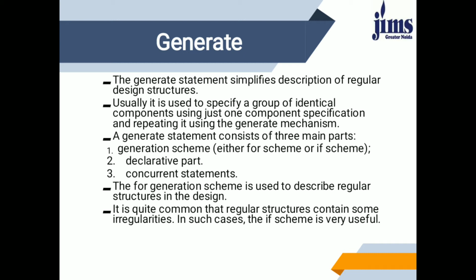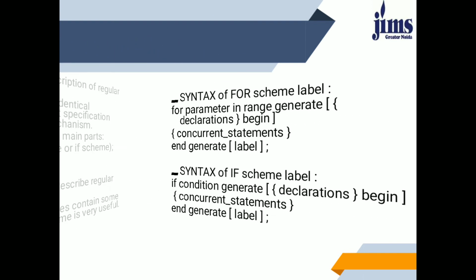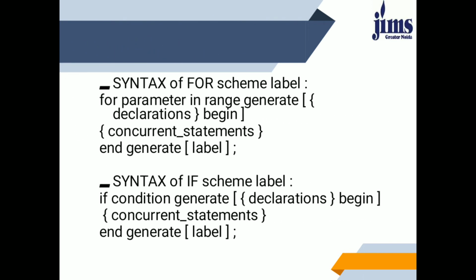It is used for repeating concurrent statements for a predefined number of times until a condition is satisfied. There are two forms of generate statement. These forms are the for generate and if generate statement. Here I have defined the syntax for both these statements.